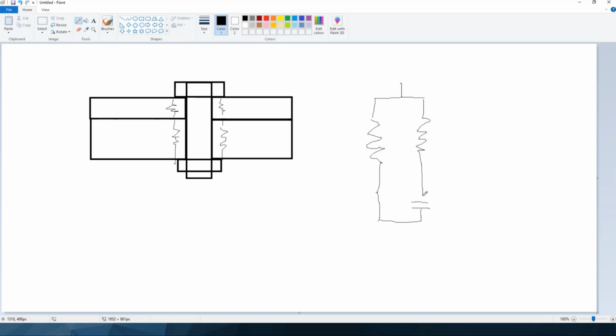There's a bit of a gap initially. So think of this nut being, as it's tightened, it's open, I move it closer and closer. And at some point, it's just touching. If I want to preload the bolt in tension, I have to apply some kind of a force down and up on that region. So that represents my preload in the bolt itself.